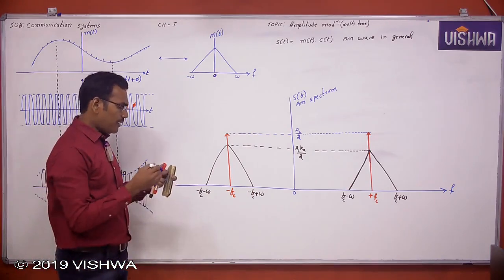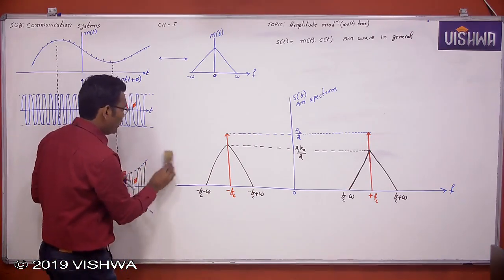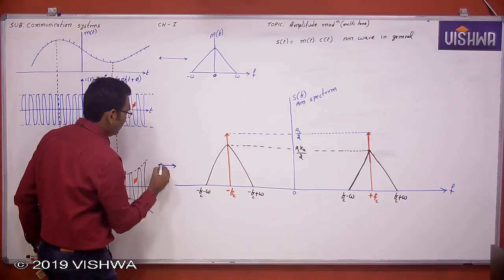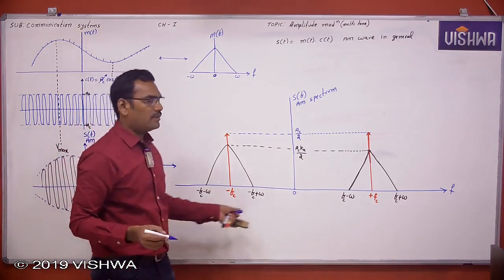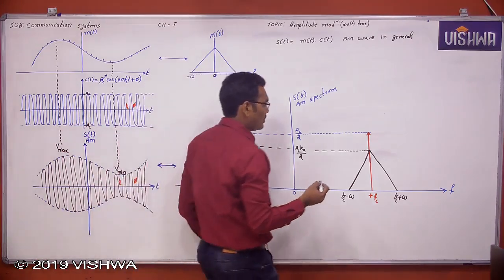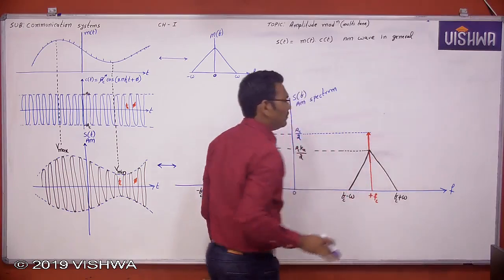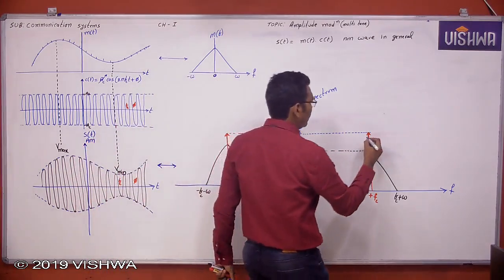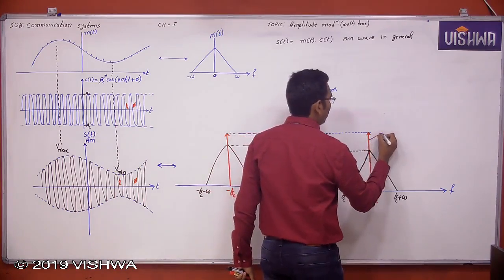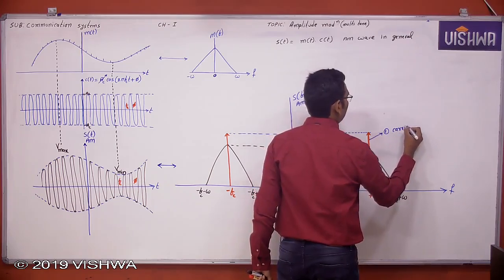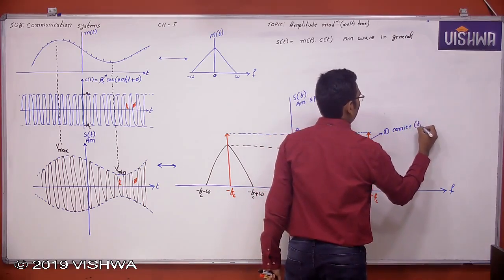But why are we finding the frequency domain here? Why are we applying the Fourier transform? For the purpose of identifying the bandwidth. Now the frequency ranges are identified here. This is the AM spectrum. If you observe, the AM spectrum consists of three spectral components. First one is the carrier, Fc.